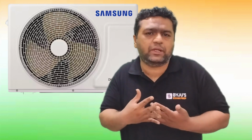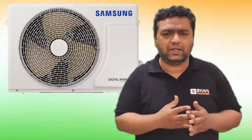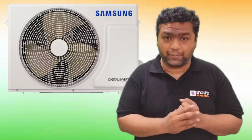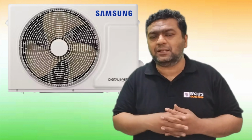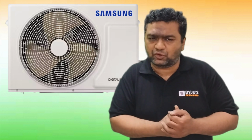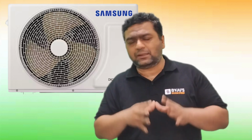From the evaporator, as you know, it has to take the heat from the surroundings, so the temperature of the refrigerant should obviously be lower than the room temperature. But when it goes to the condenser, it has to reject the heat to the atmosphere, and for that its temperature should be more than the atmospheric temperature. So in between we need a compressor, which will increase the temperature of the refrigerant. That compressor and condenser are together in the same unit.